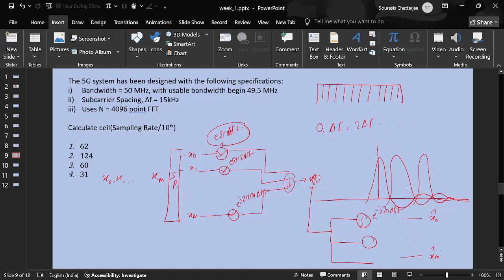So this can be implemented in analog domain. This is the integrator, and this is the phase shifter and all that. So why don't we implement it in analog domain? That looks pretty straightforward to me. Then the components will be RLC, making your circuit too heavy. Yes, the hardware complexity is quite high, even if the maths appears kind of easy.